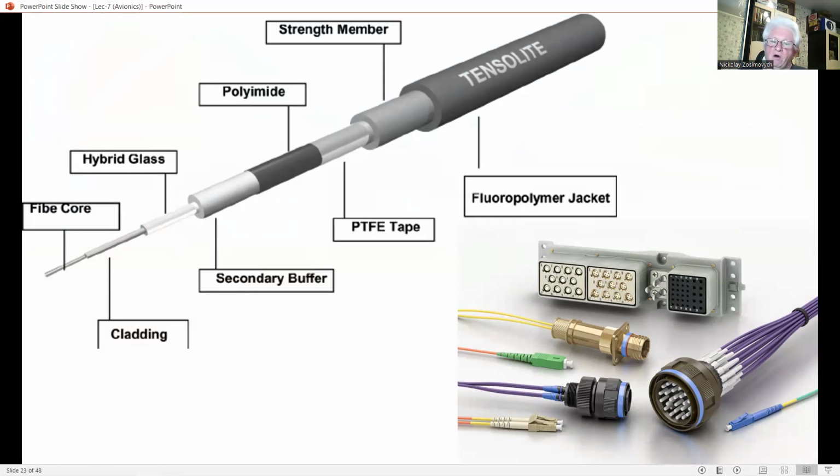A further driver of the adoption of optical data transmission is the extensive use of composite materials in the aircraft structure and the consequent loss of the screening provided by an aluminum skin, which forms a Faraday cage as far as external electric fields are concerned.